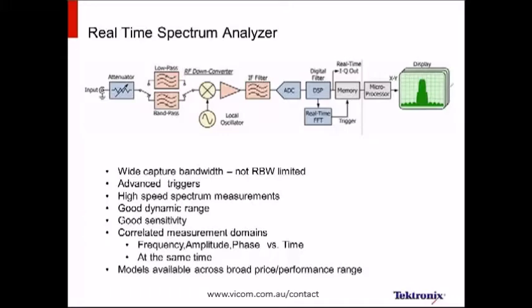And I and Q is actually going to go into a buffer as well as go into a real-time engine. The term real-time comes from the fact that we don't drop any samples after we digitize in the IF. From a speed perspective, it's significantly faster than a swept-tuned spectrum analyzer for narrow resolution bandwidths, and I have a slide that talks about that in a little bit.